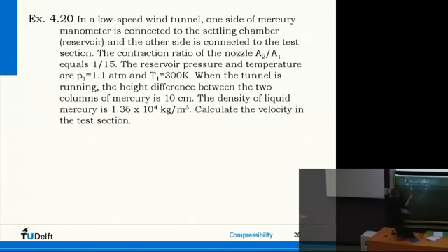Then, if these pressures are not the same, with mercury here, we will get a difference in height, right? Because on both sides we have pressures pushing, so we have a force. The force is P1 times A. Here we have P2 times A. And if they're not equal, if you think about the balance at this location, then the total force here is this P2 times A, plus the force from the mercury column.